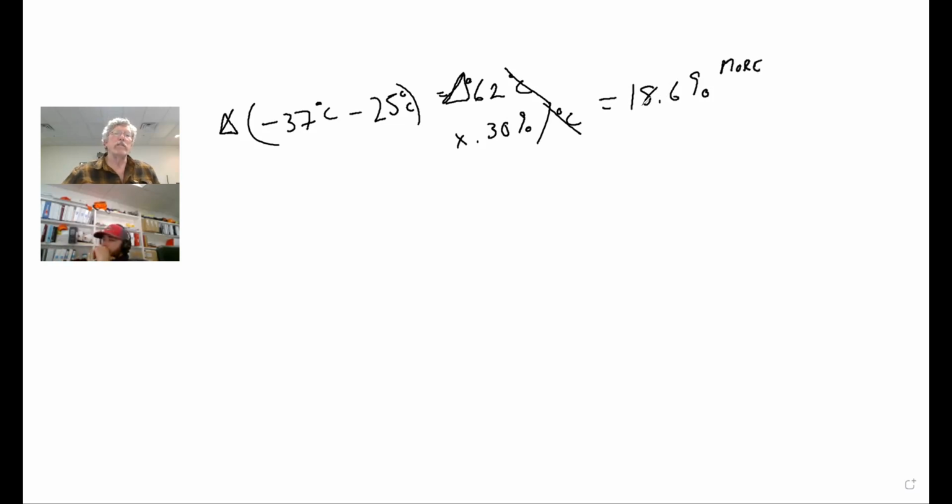voltage than it would under standard test conditions. So I'm going to take the VOC, which was 37.8 volts, times 118.6%, because I've got 100% of it, plus I'm adding 18.6% more. And I can convert this to a decimal by simply dividing that by 100, so 1.186.